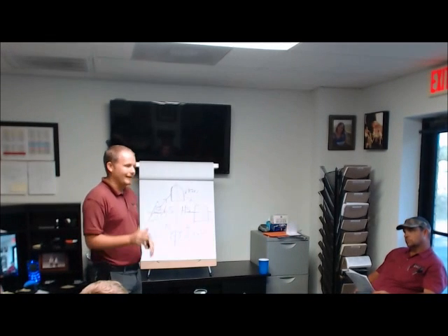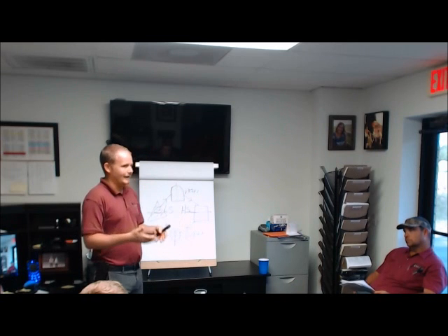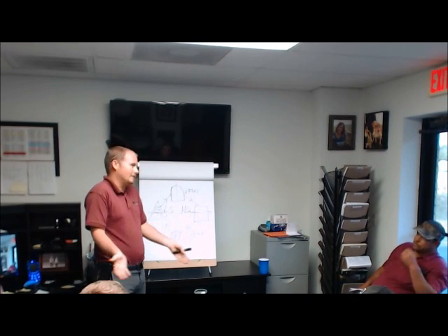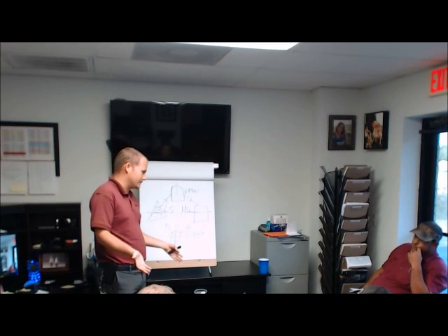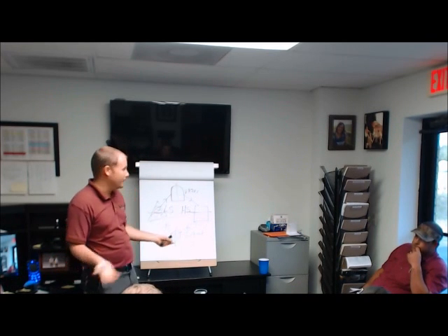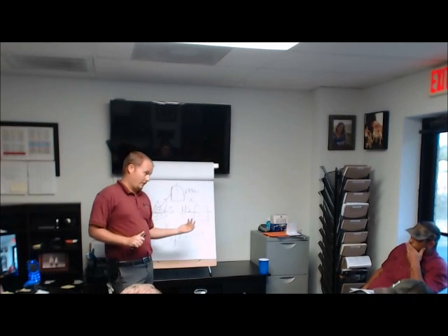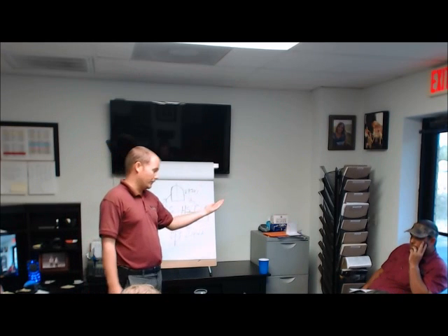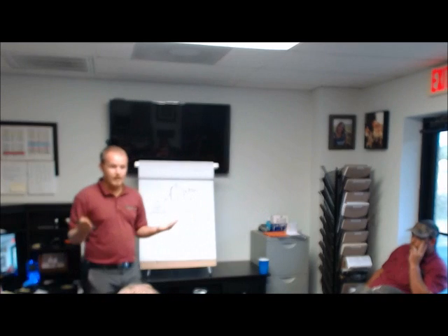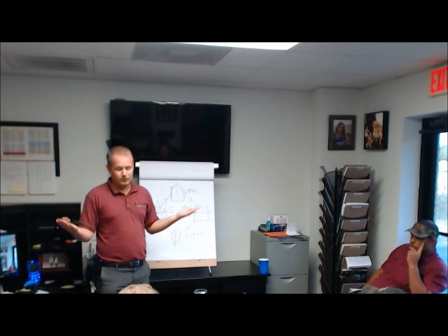Now, that doesn't tell me the superheat, and that's not enough, but when I'm in the process of diagnosis, I can tell you within 15 seconds of hooking my equipment up what's going on with the system. And I tell guys this all the time, because those are the two that get misdiagnosed the most often: the difference between a system that has low airflow and low on refrigerant. That's the most misdiagnosed refrigerant condition that exists. But I can tell you whether it's one or the other instantaneously, as long as the system's not frozen.